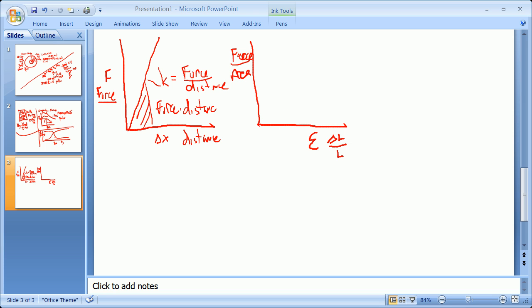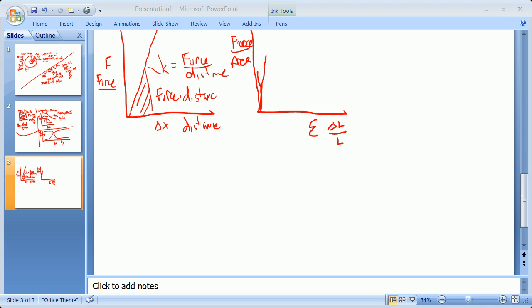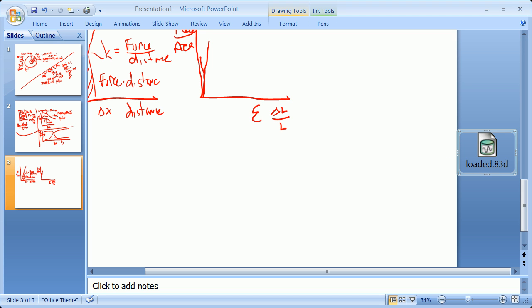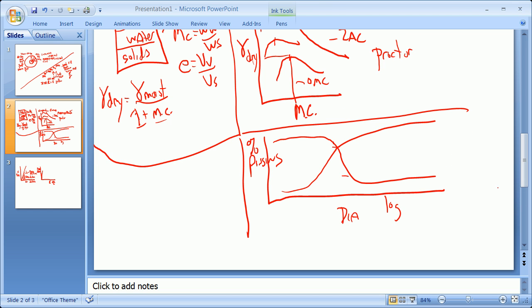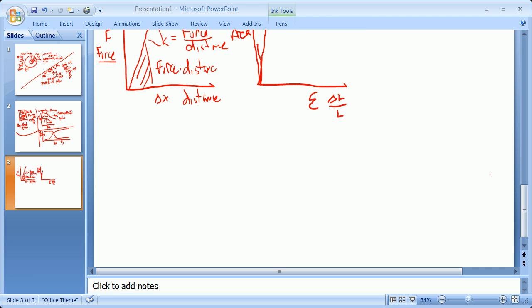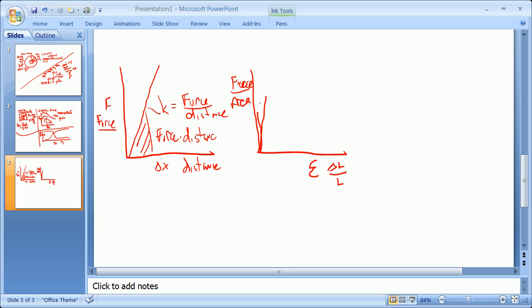Once again, in this case, we're looking at a material generally that's going to have some, hopefully, some sense that you have a linear relationship. You have a linear relationship to a point that's called the elastic, right, or the proportional zone, where effectively if you add more stress, you have strain, and then you go back and forth along this line. Eventually you get to a yield point where you have yield, or on some materials, or fracture on others, where a small increase in stress leads to a large increase in strain.